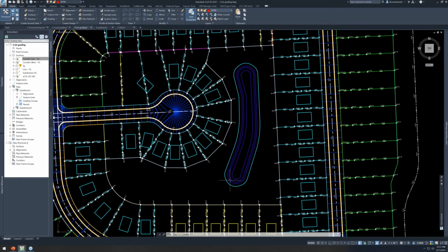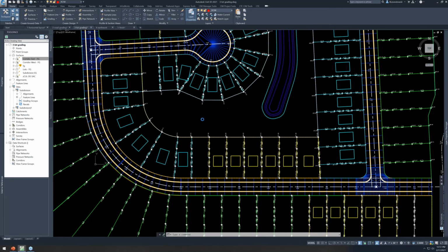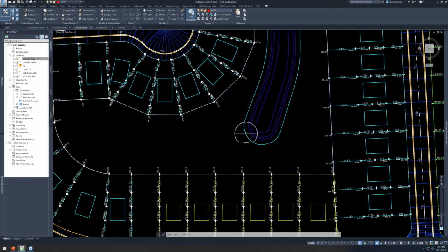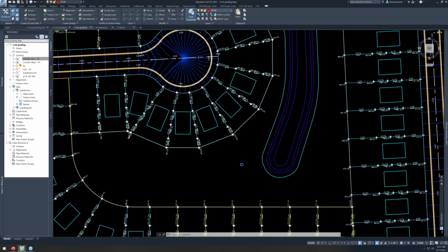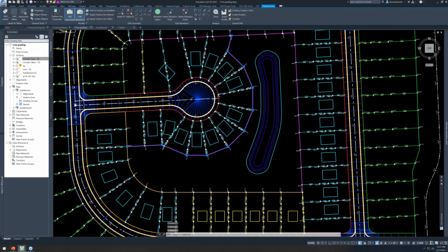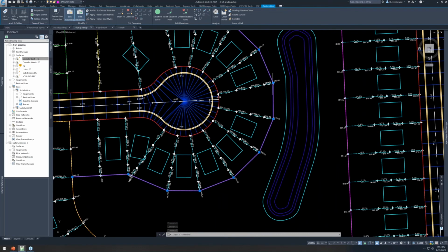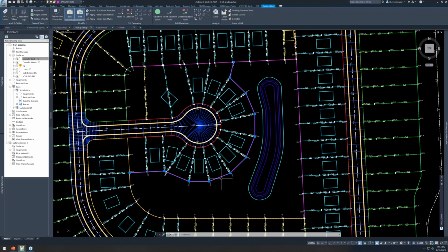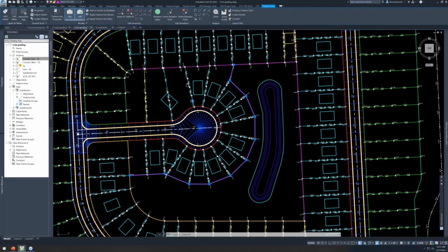Now you want a swale running right from here up to here. Draw it in just like we did a backyard swale down here, okay? Give it a style that will either move up and down as the pond moves up and down, or force a cutaway in the pond. Other things we had here was our back of lot line. Send this to the back. This feature line has a style called back of lots. I can manipulate that to control the slopes on the back of the lots here, okay. So that's the overall process we're going for here, okay.